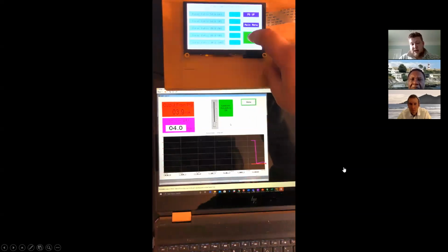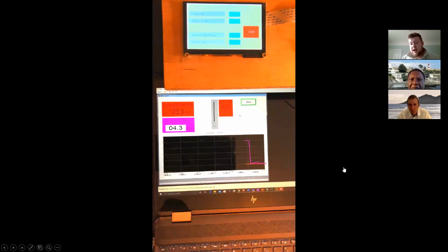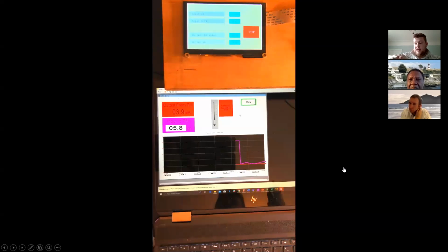So on the bottom screen, I also created a test bench on PLC using ladder code. I'm just setting it up at the moment. So I'm just going back to the system. When I click run, the output should be 0 for quite a long time until it reaches roughly 40, in between 40 to 50%. So that's roughly 10 milliamps, and then you should see the red line slowly print out the pump characteristic curve.